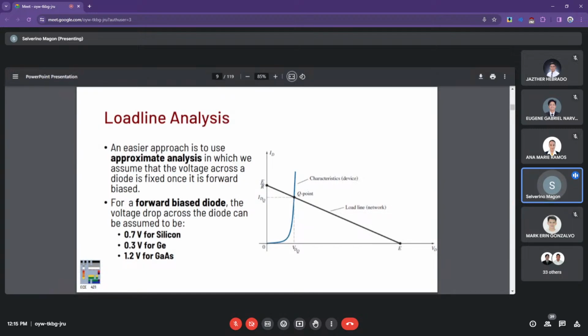So again, for a forward-biased diode, silicon-based rectifiers can be turned on by applying 0.7 volts across. For the germanium variants, that is 0.3, and for compound semiconductor-based diodes, that's typically higher than 1 volt.